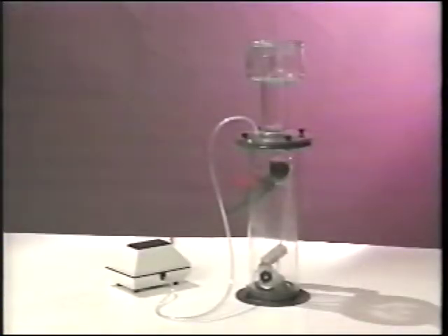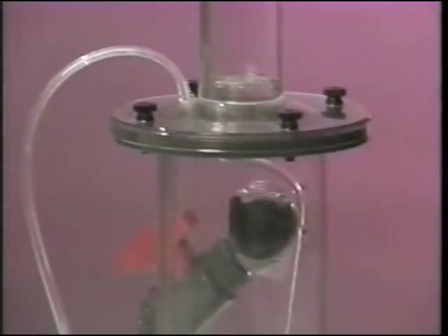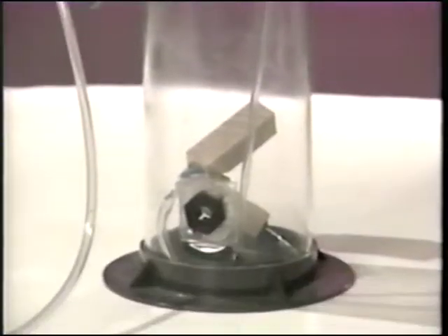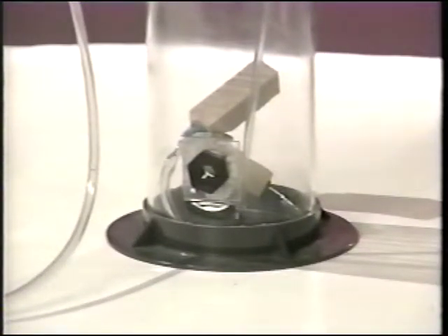As water enters the reaction chamber of the skimmer, it is met by air being injected by an air pump. As this air and water mix together, they create a foam made up of organic waste. This waste is pushed to the top of the skimmer and collected in the skimmer's collection cup. The filtered water exits the skimmer through an output valve back into the wet-dry sump area.